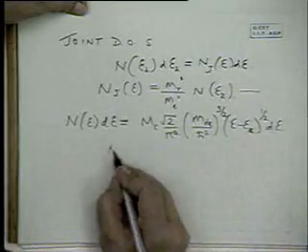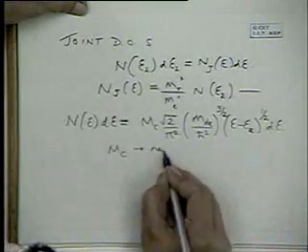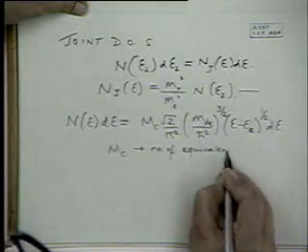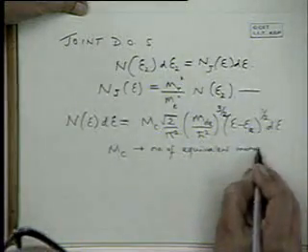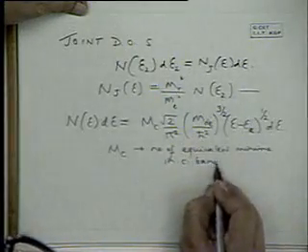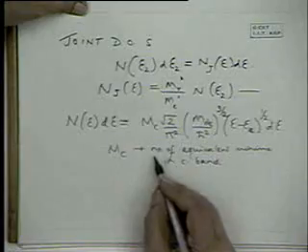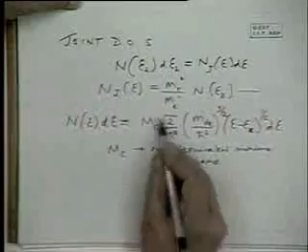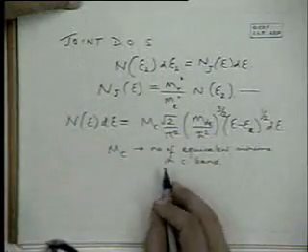For gallium arsenide or direct bandgap semiconductors, MC is just equal to 1. But for silicon there are 4 equivalent minima, and in the case of germanium, 6 equivalent minima. But we're concerned with direct gap semiconductors, so MC is equal to 1.